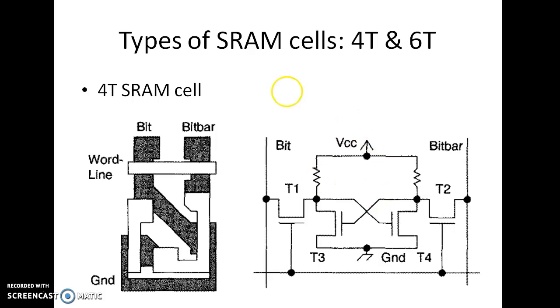Means a resistor. You know that to fabricate a resistor you require more space than a MOSFET, because a MOSFET is very compact, you can fabricate it in less area. And moreover, if you want to change the resistance from 1K to 1 mega, for example, you need to fabricate a 1 mega ohm resistor separately, and it would take more area when you increase the resistance size, right? So that is a major drawback of the resistor.